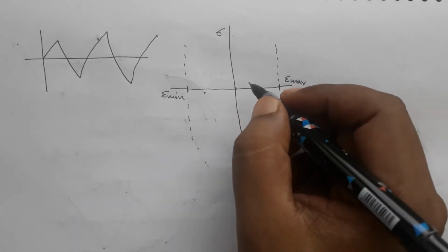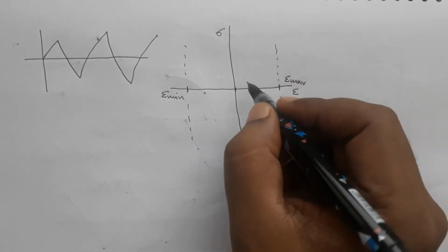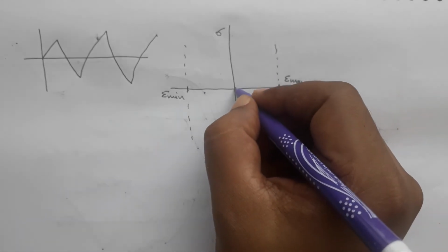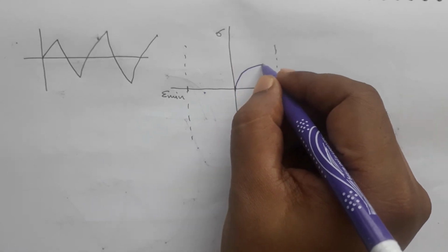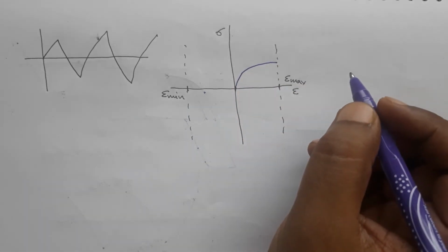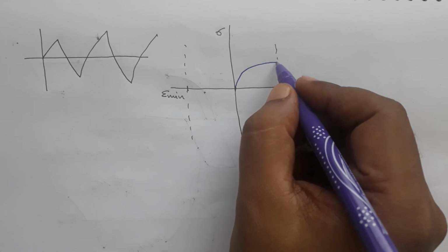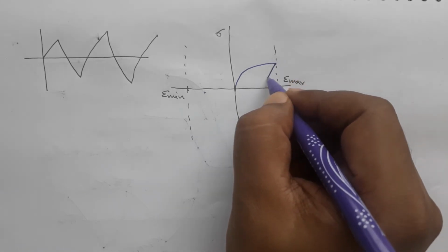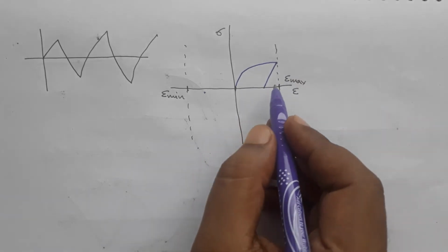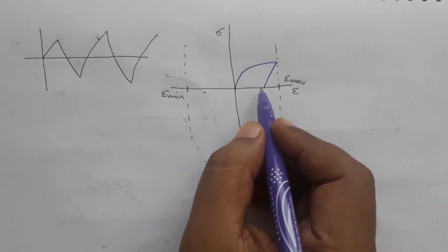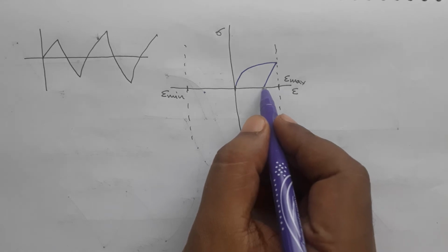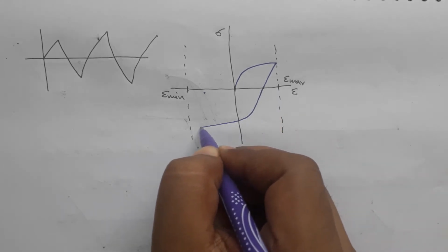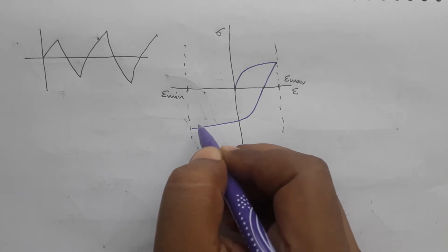So if it is cyclically hardening, you will have something like this. You will have initially linear elastic, and then the material will deform plastically, right? And then you will unload it, and then in the next cycle it will deform at a later stage and go to that strain value.